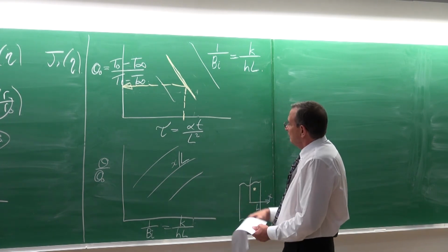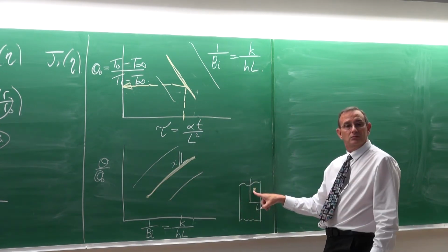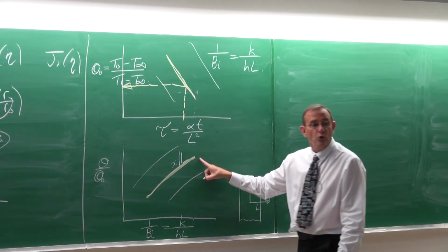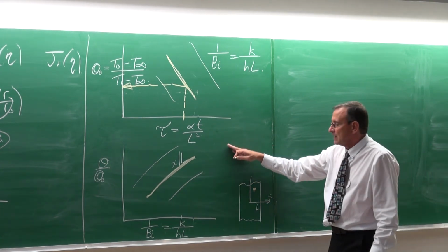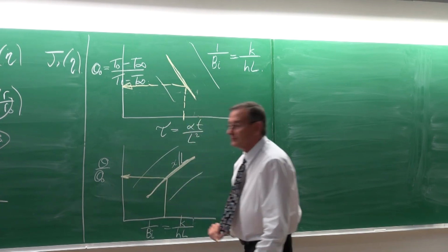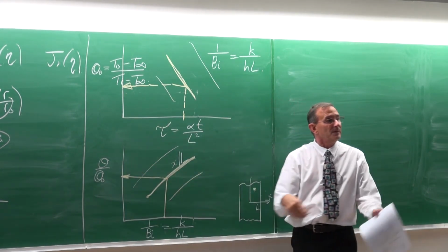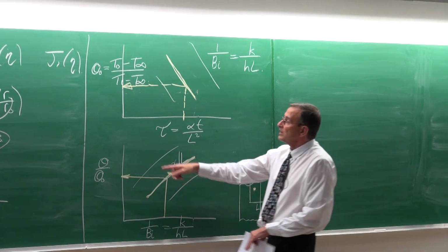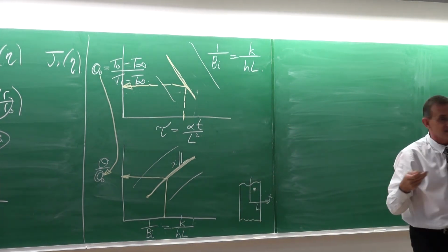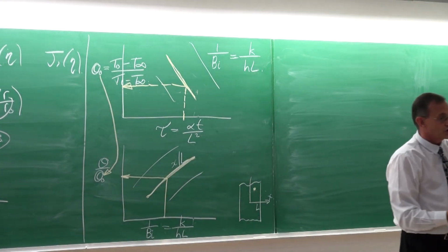Again, if we now look at this, we can identify from the x value. So in this case, it will be x divided by L is equal to 0.5. You can select the graph. The Biot number, you can get there, and then you get that value. Okay. Theta divided by theta 0. This means that if you want the temperature inside the body, you always first have to calculate theta 0. Okay. First get the temperature at the center. With that known, you can put it in there, then you can calculate theta at any other position in the body.